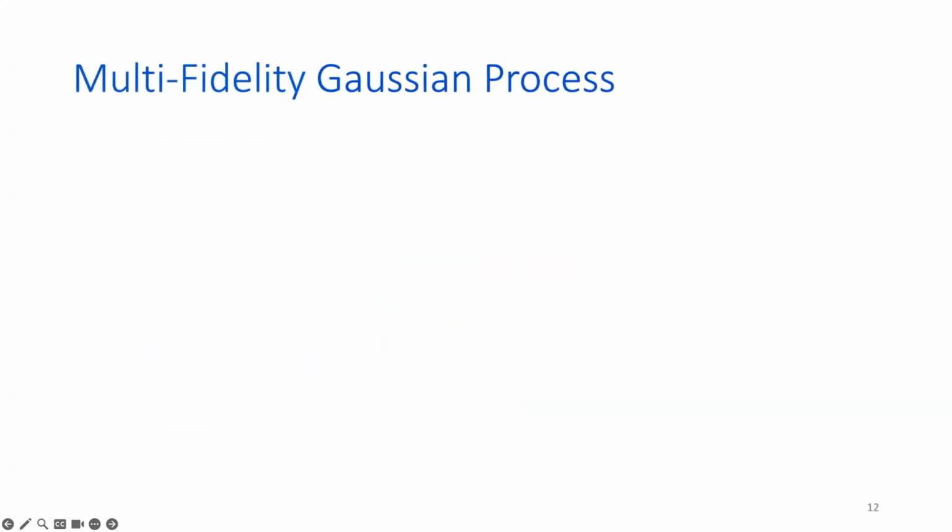The model that we're actually interested in is the multi-fidelity Gaussian processes. In this case, I'd like to combine Gaussian processes together as building blocks to create a model that can combine data sets of different fidelities. The fidelity of a data set can be defined as a combination of the data's precision and accuracy. The most accurate set of observations with the highest resolution are referred to as the high fidelity data, and the less accurate and coarse observations or simulation data are denoted as low fidelity data.